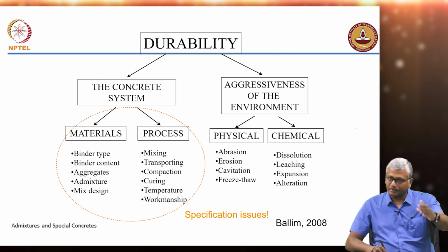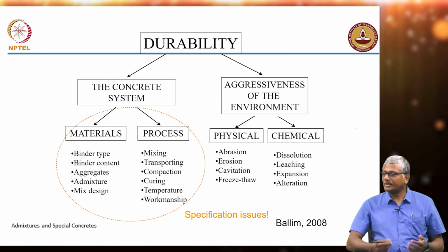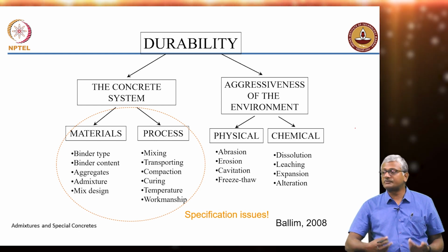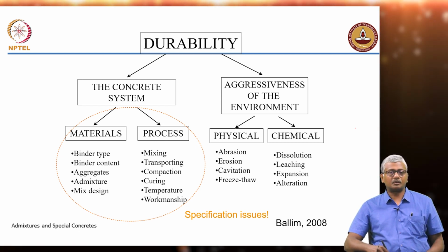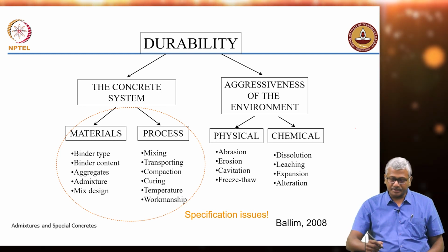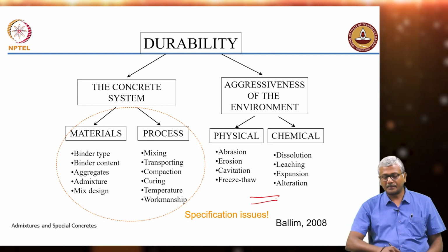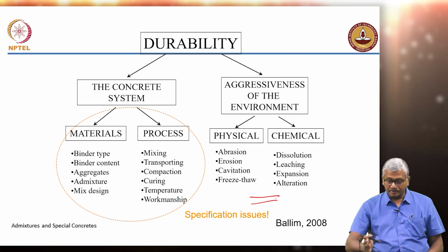If you go further inland, you do not have any chlorides, but then atmospheric carbon dioxide can penetrate the concrete and lower the pH of the concrete, causing corrosion. So, all of those things you need to understand and design for. There are physical mechanisms and chemical mechanisms.